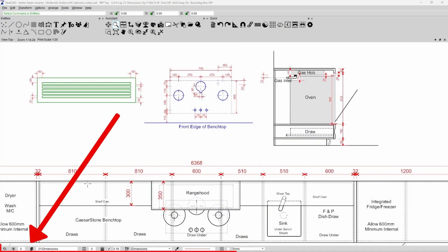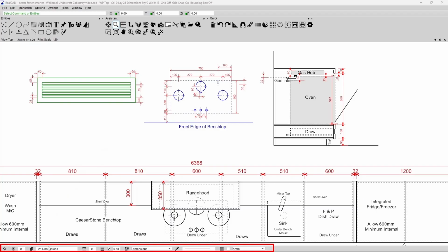In this video, we're going to look at the concept of the properties toolbar. These are the general properties of the software. This is where you set your color, your layer, your line styles, and your line weights. And it's also where you set your grid or can select grid options. By selecting any one of these icons, you will invoke another menu.